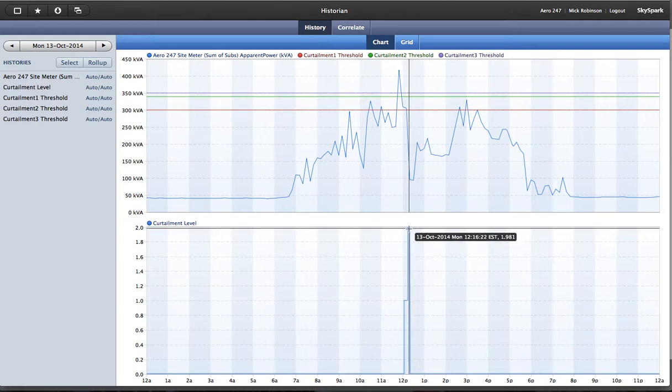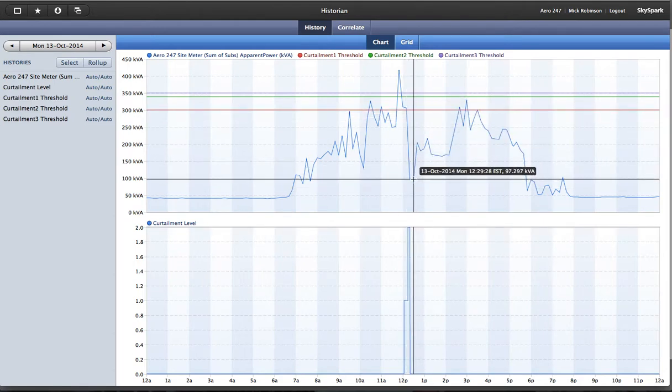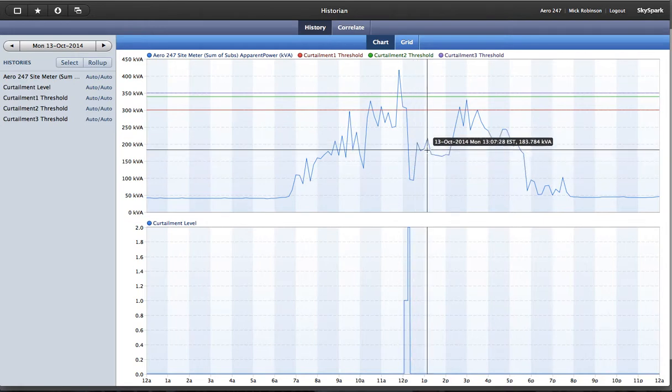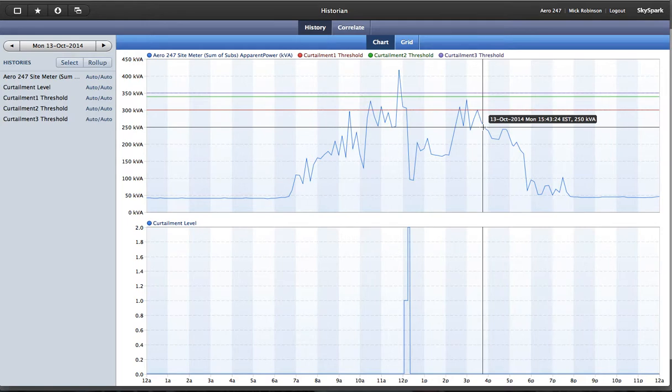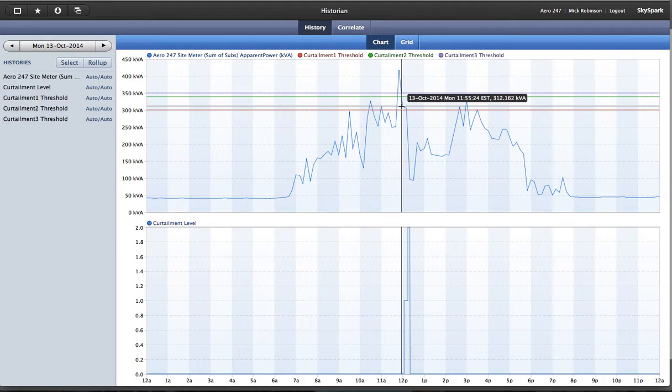So we see we've spiked up here, curtailment level 2, and immediately we've seen a very aggressive drop in the demand. And then the curtailment plans have reviewed, seen we're happy with the level of demand, turned the curtailment plans off, and the HVAC has just come into full normal performance, stabilised back to their normal load profile. So we've been able to prevent this spike, so it hasn't come through in the billing at 413 kVA. We got to it quickly enough to bring it down that the average kVA is below the chargeable threshold targets that we wanted to set.